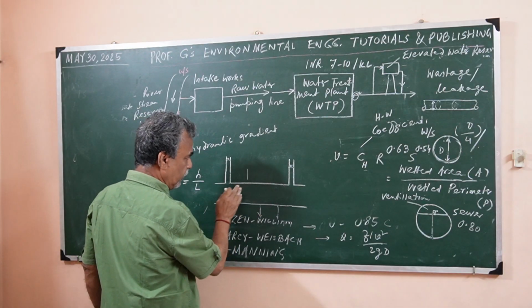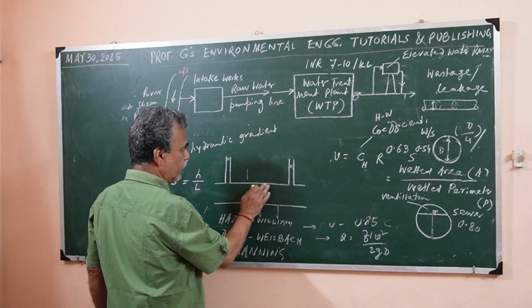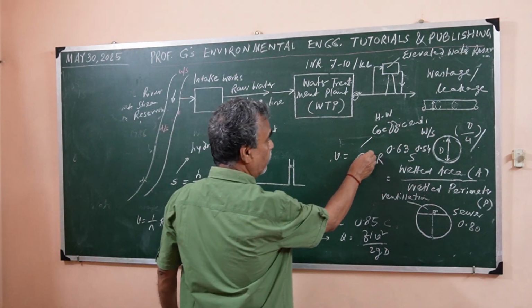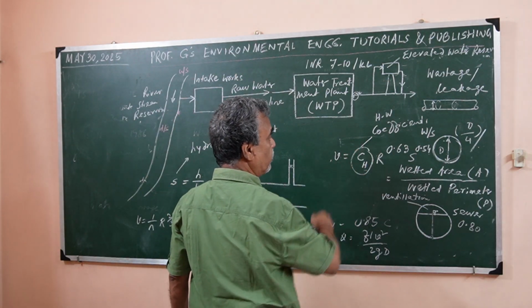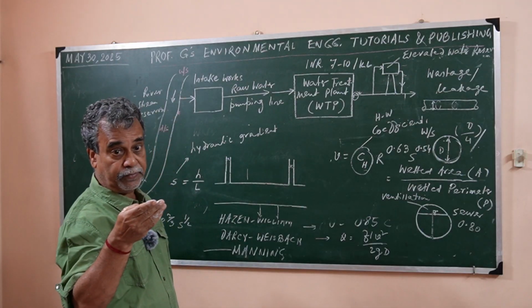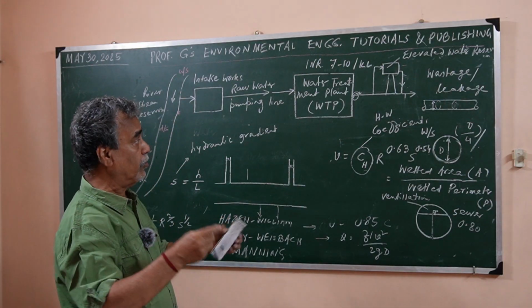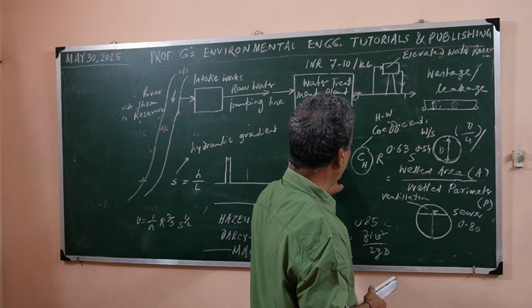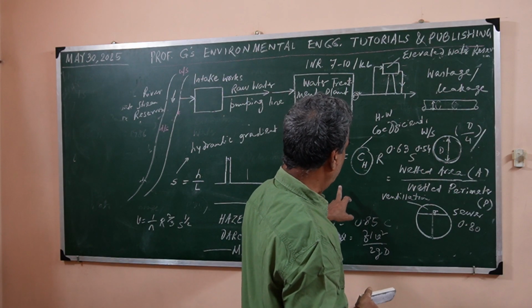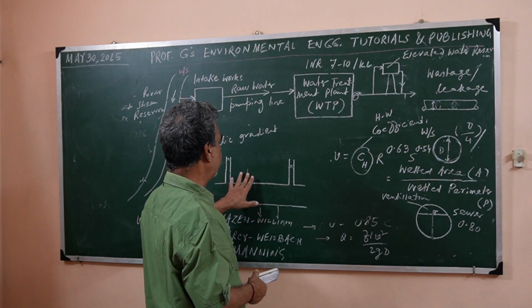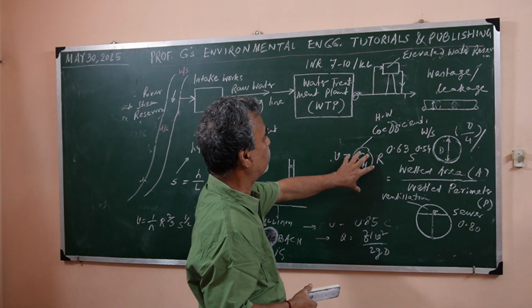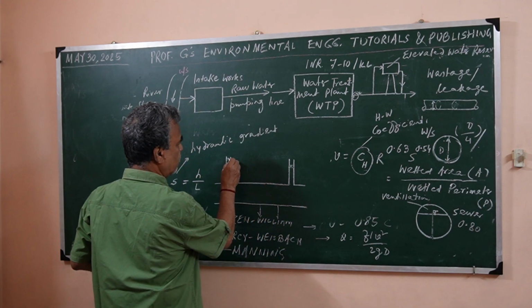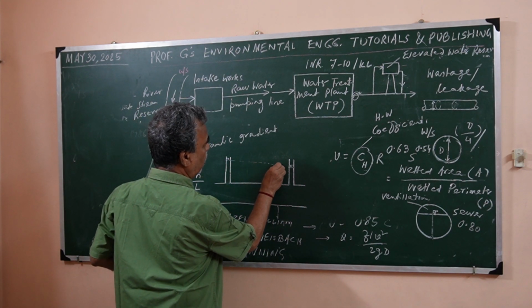So friction, when the water is flowing, depends on the pipe roughness, right? So that is the Hazen-Williams coefficient. This depends on the pipe material, then the age of the pipe. As it ages, this will reduce, so the velocity will reduce through the older pipes. For a newer pipe, this will be much higher. So what will be there? This is the hydraulic gradient.